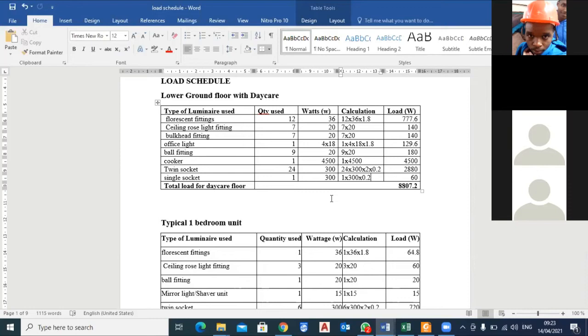7-way is there. There's some other manufacturers that work on a 7-way, or you can use an 8-way or 9-way. In other words, you cannot use a consumer unit which has less than 6 ways, less than 6 spaces for breakers. Lazima tutumie ile yenye ni 6 and above. I will urge you as a designer, you should recommend for an 8-way or a 9-way. Why? For spare purposes.